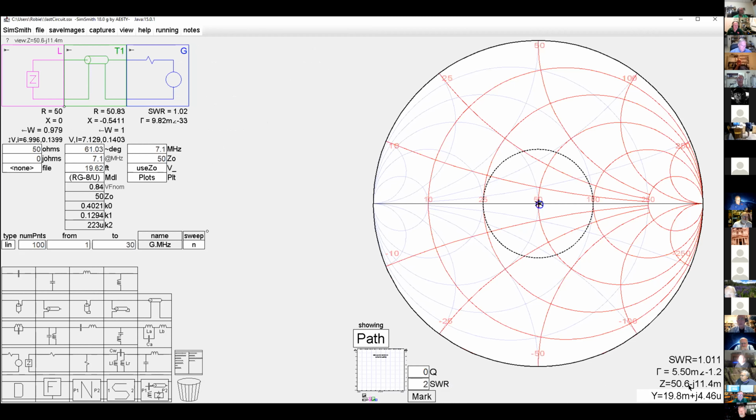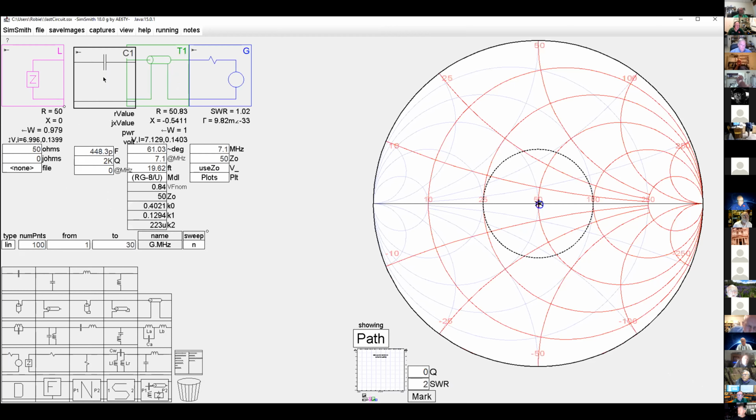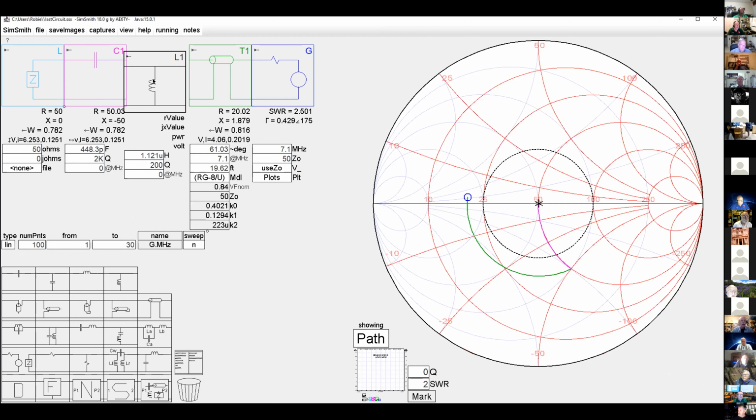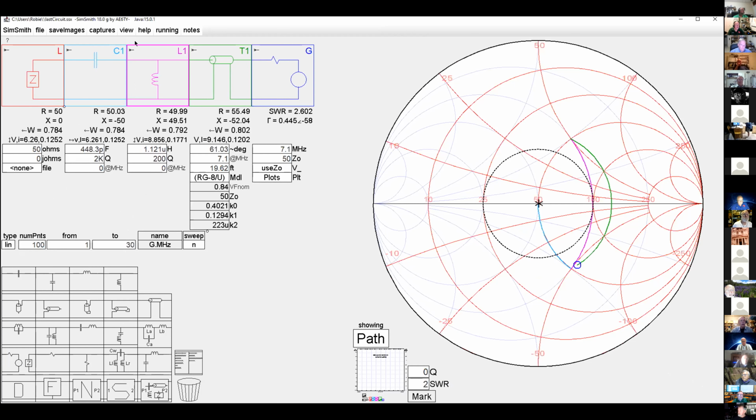From the figures in the lower left-hand corner, can this also handle tuned circuits? Say again? The figures in the lower left-hand corner, can this also handle tuned circuits? Okay, it's a good introduction, Doug. So these are circuit elements. This is more than just a transmission line. This is a general ladder circuit analysis tool. A ladder circuit is things that are in one line. So I can put a capacitor in series with my load. I can put in a shunt inductor, which, if you look at this, is an L network, right? That's how you build matching networks.